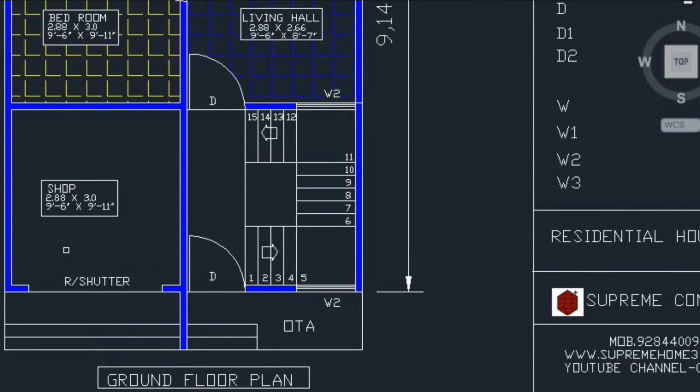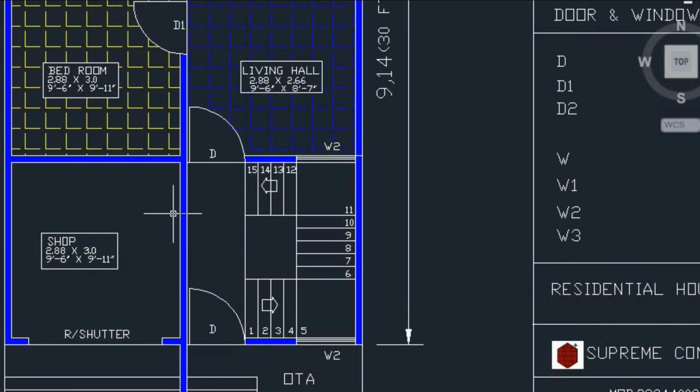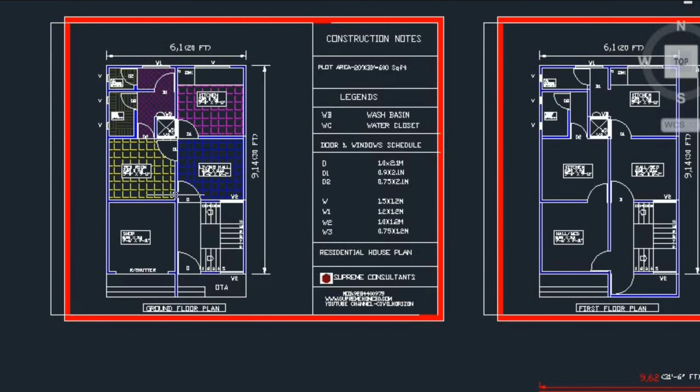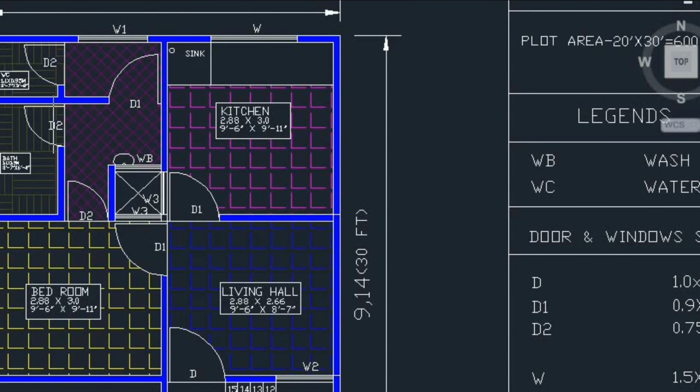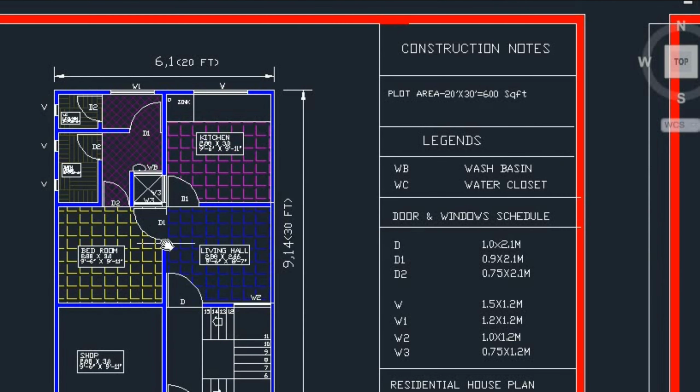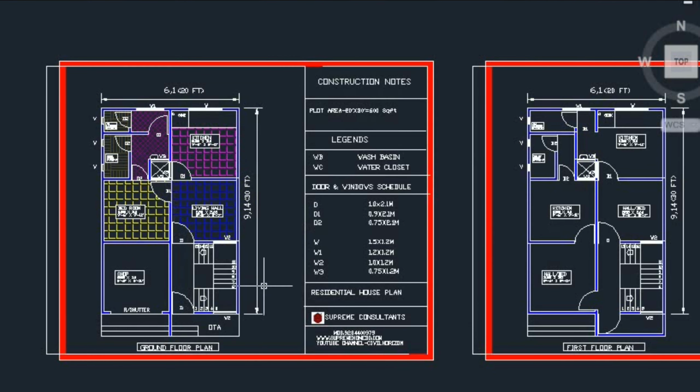Architectural design features. So I have planned the entire building floor wise, and what I have considered is all the rooms are as per the client requirements. Stair is planned in the front portion because it gives an elegant look and easy access to tenants without causing any disturbance to others. Duct is provided for light and ventilation purposes near washrooms and kitchen.